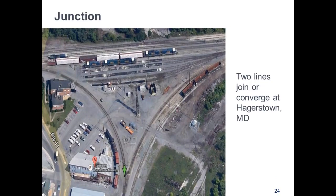So moving on, another way to add capacity for a single track railroad is at junctions. A junction is a place at which two or more rail lines converge or diverge. Yeah, 2 ways to add capacity to a junction are these. Locate a passing track immediately off the main line at the junction. So if there is an inbound and an outbound train, you have a place to park the outbound train while waiting for a potentially late inbound train to arrive, or vice versa. At high density junctions, typically with double track, installing parallel routes so inbound and outbound trains can meet at the junction without stopping helps a lot.